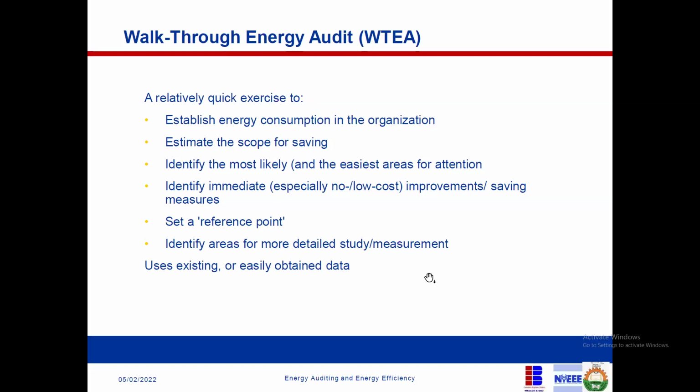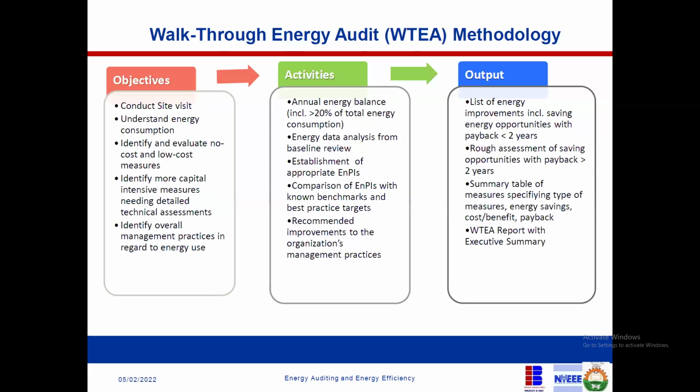If you have solar, for instance, I'll look at whether the solar is connected to your inverter, or whether I can recommend you having a solar submersible pump that will stand alone for itself. Or I'll look at other areas, maybe while pumping, you should turn off the refrigerator, for instance, assuming you're having a problem. So these are what we do in a walkthrough audit.